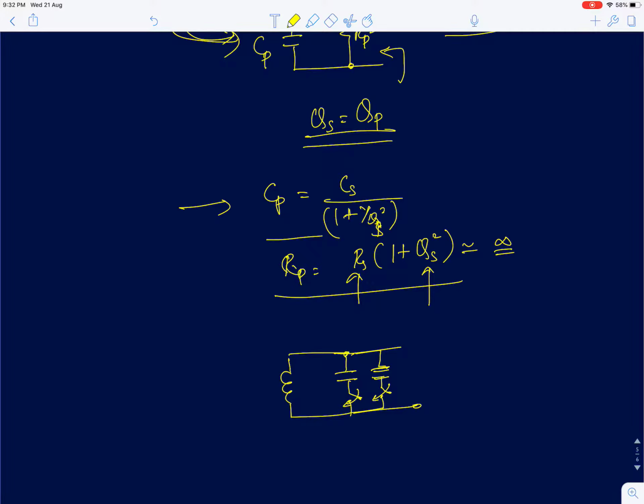Okay, and that actually is a little bit more complicated analysis. It actually has an effect on the overall noise of the oscillator. So it's important to model the series resistance, and it's important to know some parameters which can tell you how good your capacitor should be. Based on that, you can design your capacitor. So we talk in terms of Q. Instead of talking about series resistance Rs mainly, we will directly use the word Q. Okay, if you want to compare two capacitors of the same value, I'll just directly use the word Q to compare how good the two capacitors are. If they have different Qs, then the one with the higher Q is a slightly better capacitor. So that's the conclusion from this lecture. So I'll stop at this point.